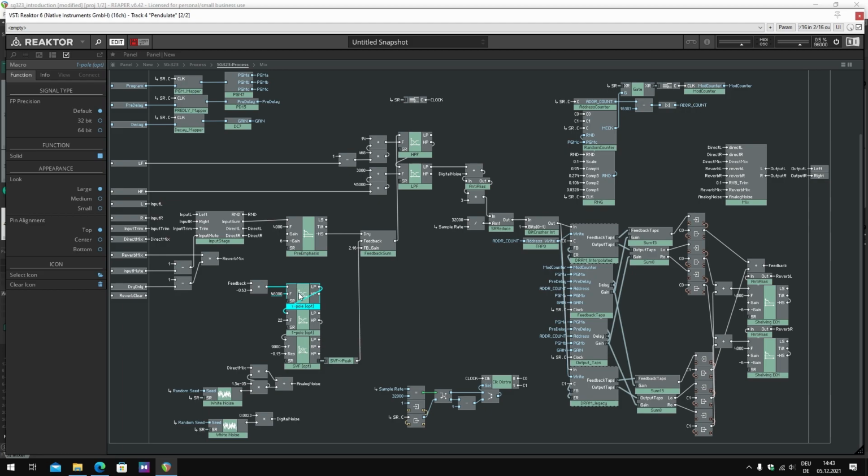Then we have a 48 kilohertz low pass filter, which is just a one pole. Same for a simple high pass filter. And this is a dip filter at 9 kilohertz, so it's really small. Even in the original circuit, it doesn't do much, but I guess it's needed to tame some of the resonance or some of the feedback overshoot.